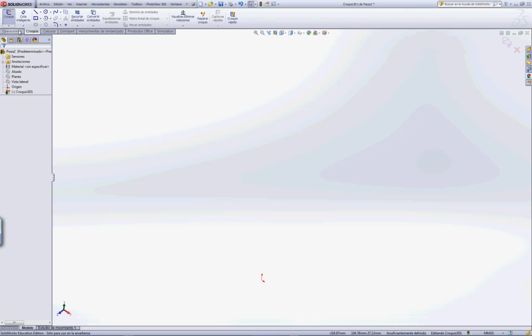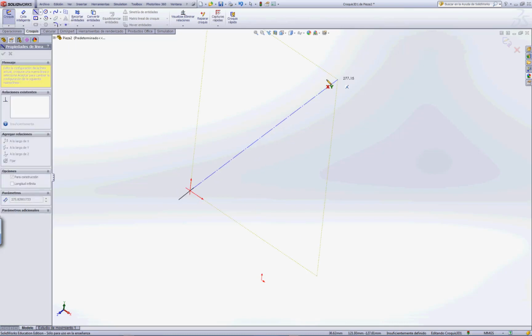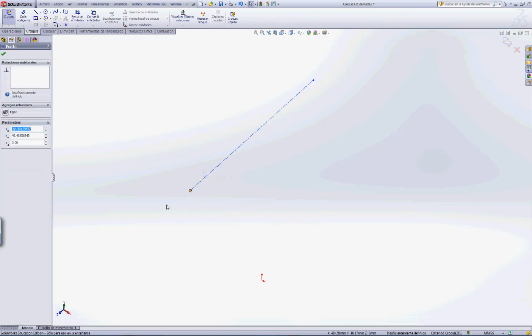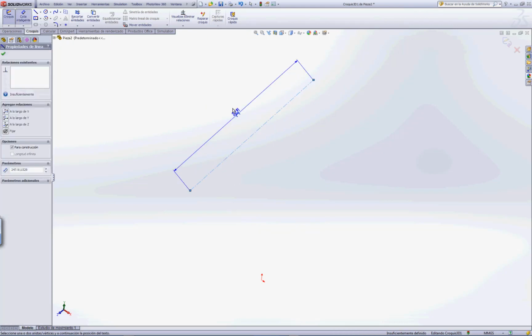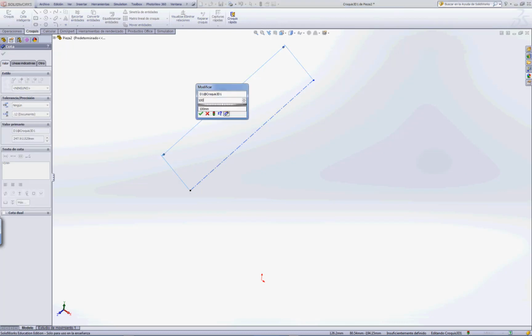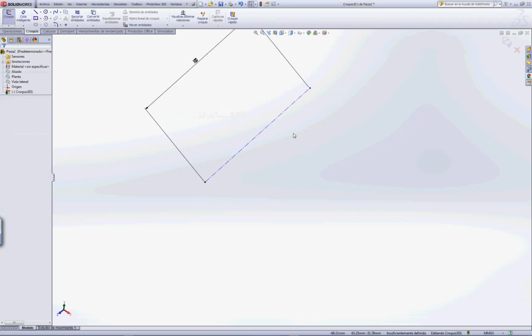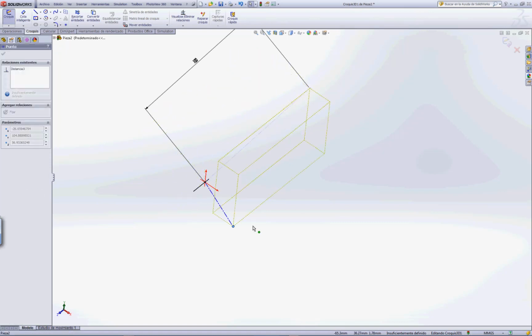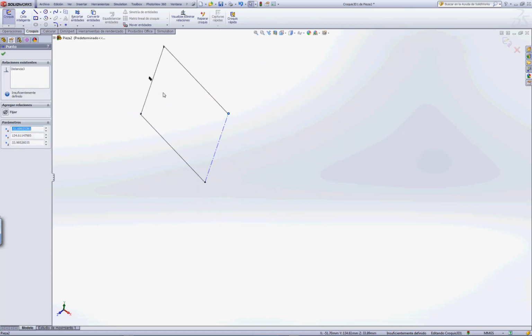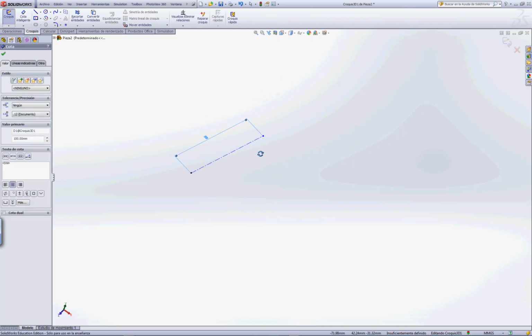Well, to do so, we are going to draw first the radius of the sphere. We are going to fix the center, and we are going to set the dimension of the radius. I set it to 100. So now, if we move around the floating point at the end of the radius, we can visualize that it is defining the surface of the sphere, a sphere that is not visible yet.